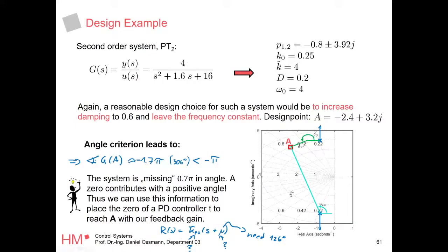So you would need 0.3 times 180, which is about 50 degrees. So 50 degrees is, you would add a pole here, right? This would be roughly 55 degrees, right? Now, however, you would need to go with positive feedback, right? And remember, the root locus curve will change with positive feedback. So what will happen is, okay, now I need to think, these guys will go here.